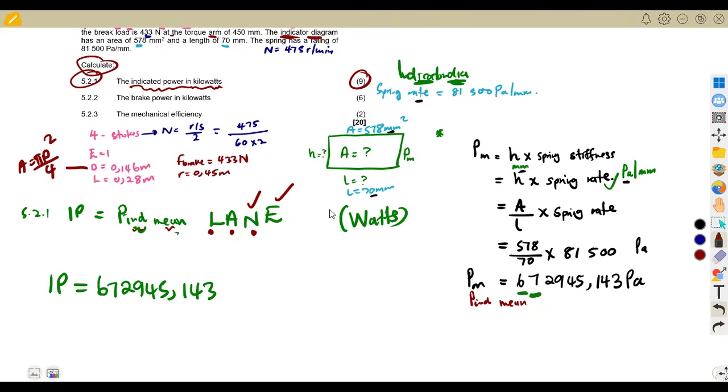So now to have the answer in kilowatts, you multiply by 10 to the exponent of -3, which you could have done here. So we are going to do it in our calculation here. Like I said, the L is for the stroke length, which is 0.28 in meters, times the area, that is pi d squared.